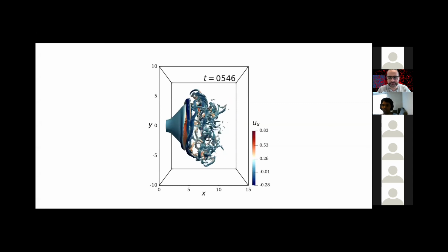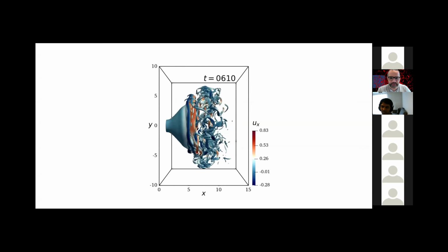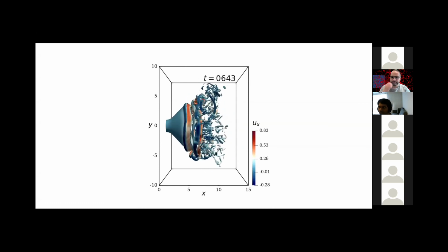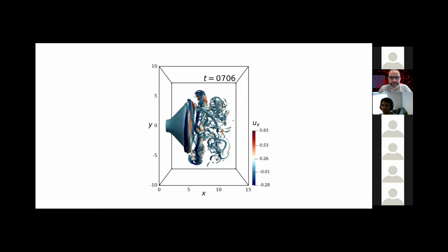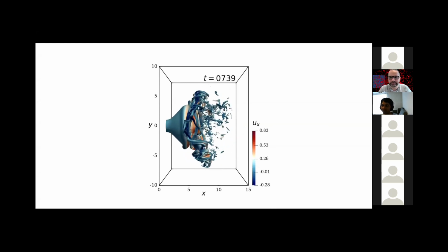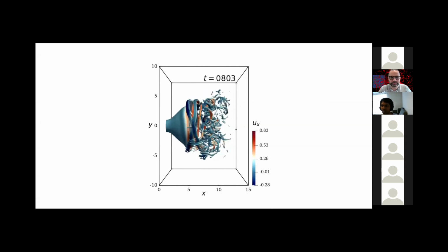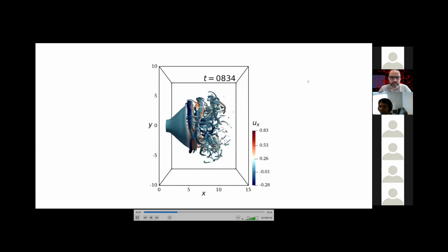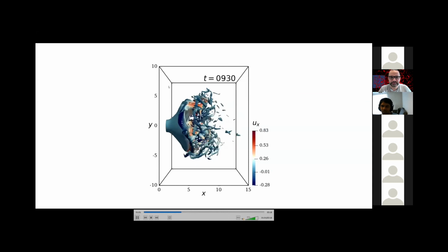I didn't mention this, but we are actually using a buffer zone at the outflow. You can use the same filters that you're using for the LES, but selectively filter in the region close to the outflow. Because of that, you can suppress any recirculation zone. The first aspect is to include co-flow.